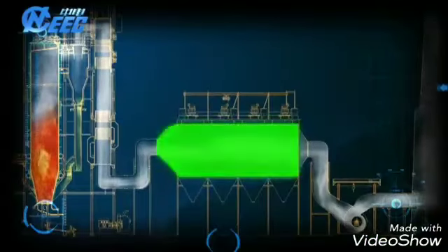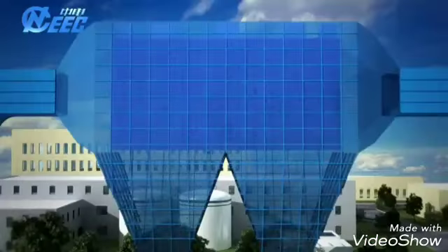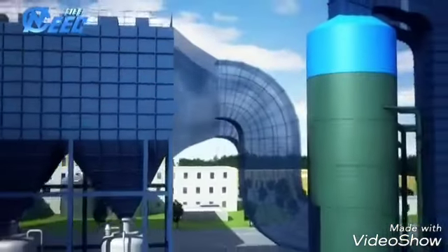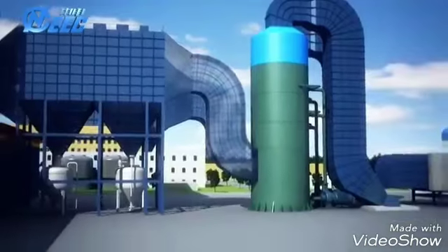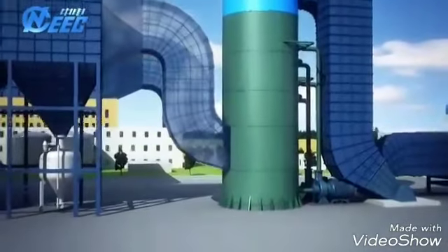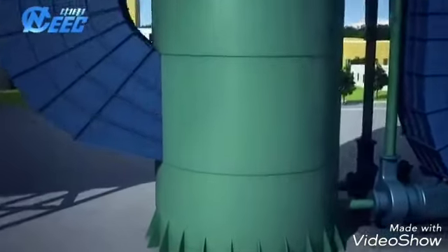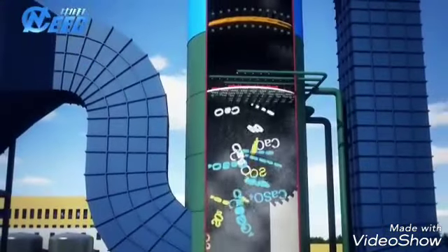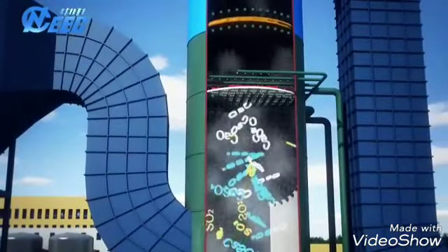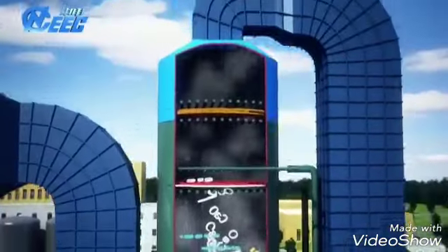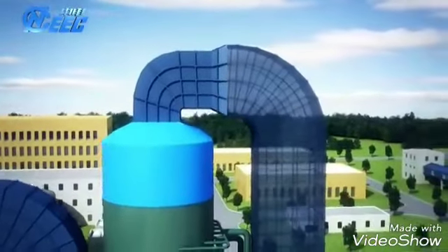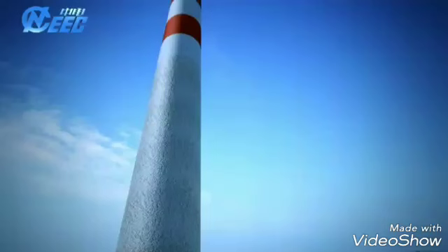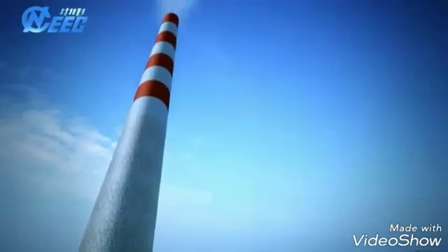Flue gas is cooled in rear flue pass and gets into electrostatic precipitator for dust collection. Secondary desulfurization system is designed for flue gas system. In the system, flue gas flows into desulfurization tower. Sulfur dioxide in flue gas reacts with calcium oxide to plaster. The treated flue gas is discharged from the chimney into the air by induced draft fan.